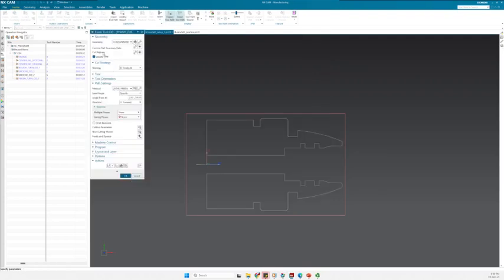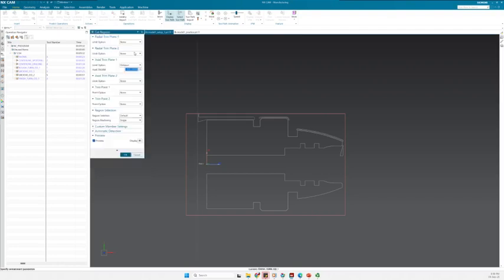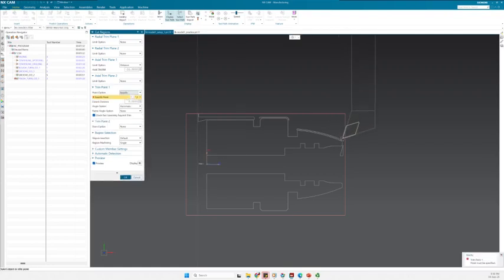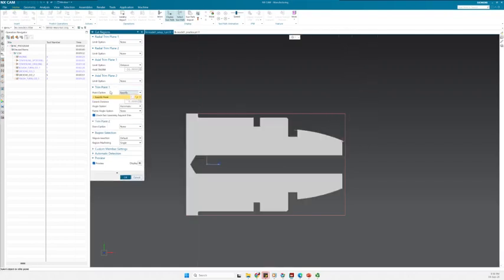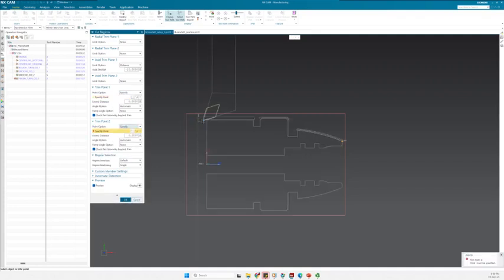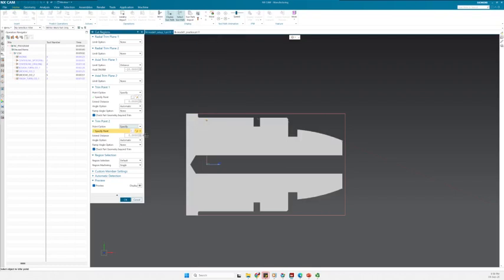So for those ones, I need to define the cutting region. First of all, I need to define the range. So I will get to the axial point 1. I will specify it from the beginning. I want it to be machined from here till specify point number 2, which is here. So I don't want this plunging to the part where I have the material for the cutting. So I have it till here.